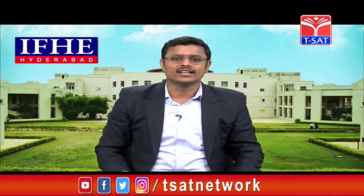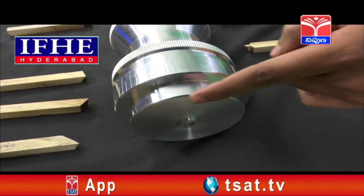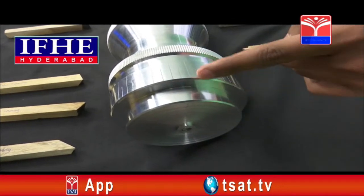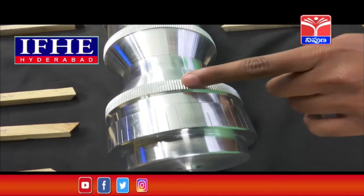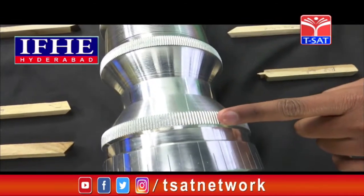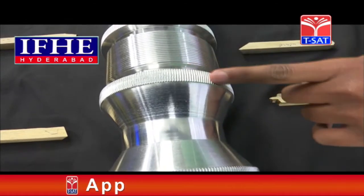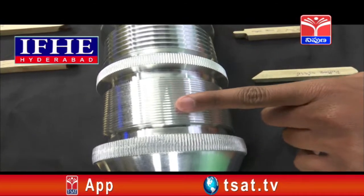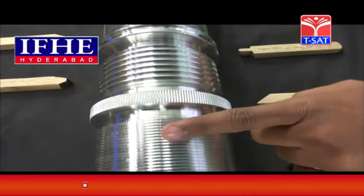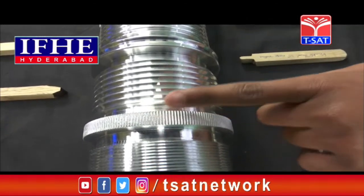So, let us see practically how this rod looks. This is facing, this is chamfering, this edge is chamfering, step turning, you can see the step here, and this is the graduation marking, and this one here you can see the straight knurling operation. This one is taper turning, and again this is a straight knurling operation. This is BSP thread, and then it is a straight knurling. BSP means British Standard Pipe, and this is straight knurling.